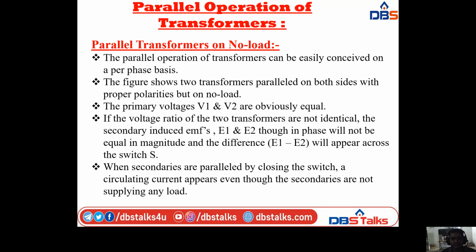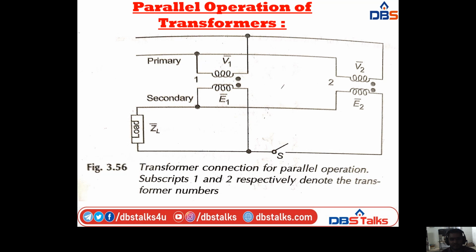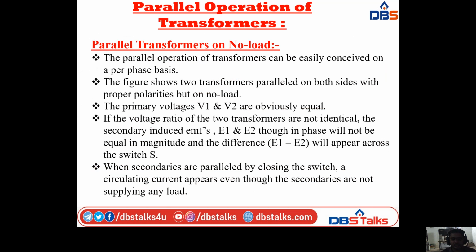Next, if the voltage ratios of the two transformers are not identical, then the secondary induced EMFs, that is E1 and E2 for each transformer, though in phase, will not be equal in magnitude, and the difference E1 minus E2 will appear across the switch.